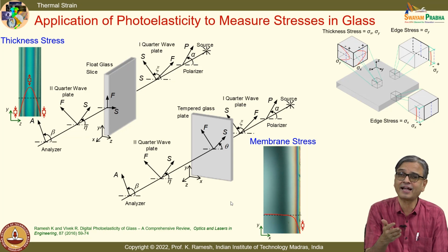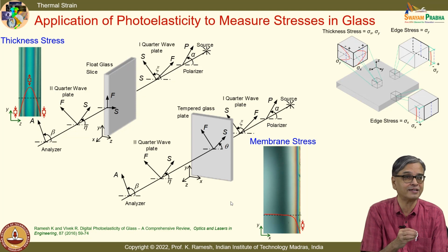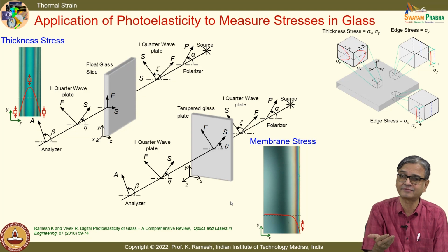By using a CAT scanner, you can generate a complex 3-dimensional model with pores and all the pebbles and aggregates put inside, and you can analyze what happens. So, you can go to heterogeneity. And we have also looked at a soft material like skin, where they want to do the epidural injection. Soft material means you need to go for finite strain. There again photoelasticity is applicable.